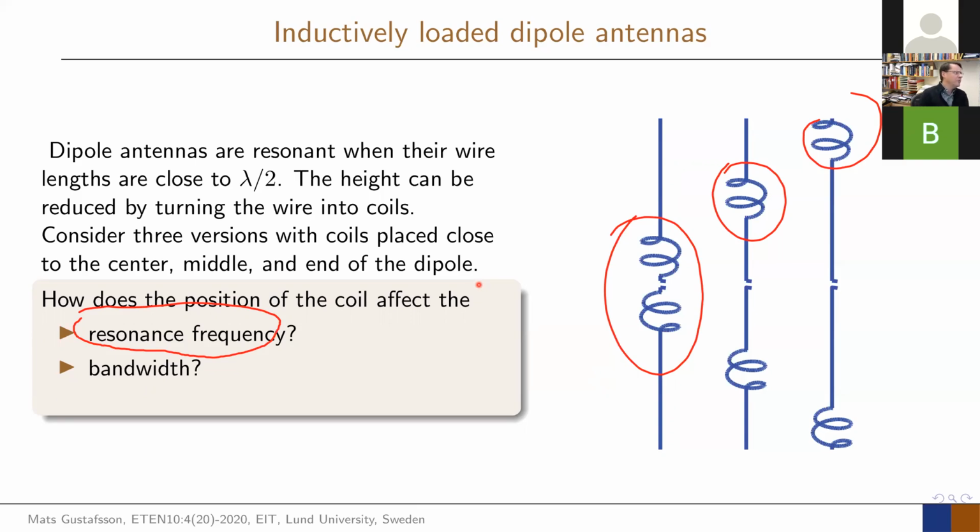What can happen with the bandwidth? We have not studied that in detail, but we had learned one thing, that was fat is good. Fat is not only good to eat sometimes, it's actually good for the antennas. And what I mentioned there is that the most important part of that was actually that you wanted separation of charge. So you wanted plus charge there and minus charge there.